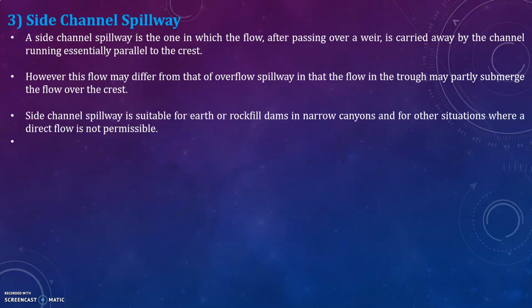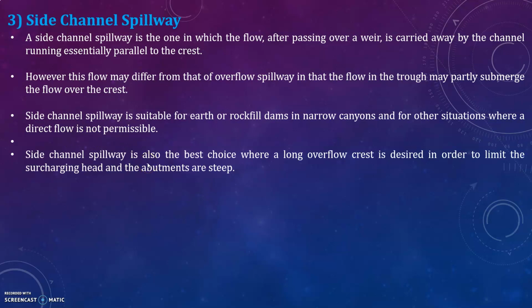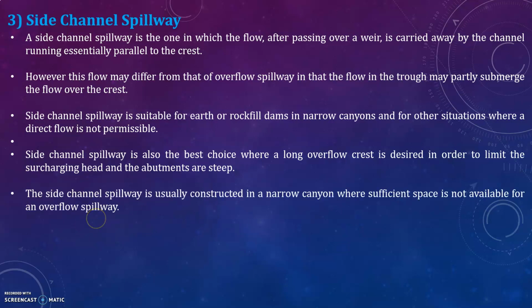Side channel spillway is suitable for earth or rock fill dams in narrow canyons and for other situations where a direct flow is not permissible. Side channel spillway is also the best choice where a long overflow crest is desired in order to limit the surcharging head and the abutments are steep.